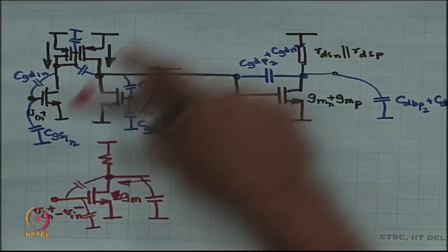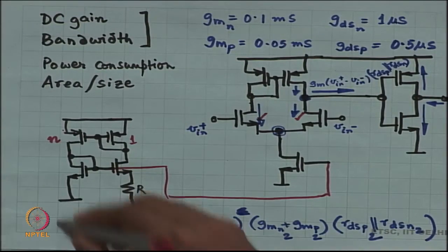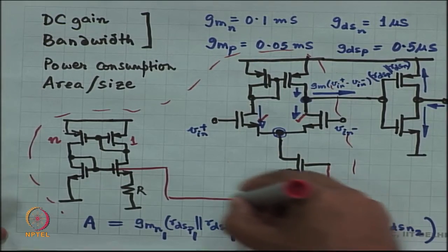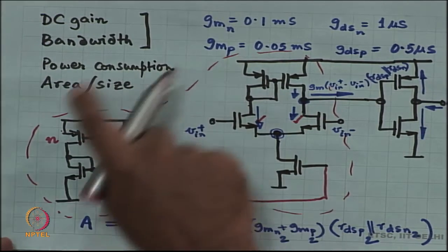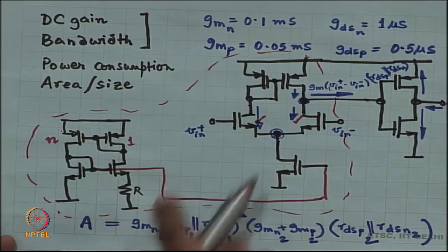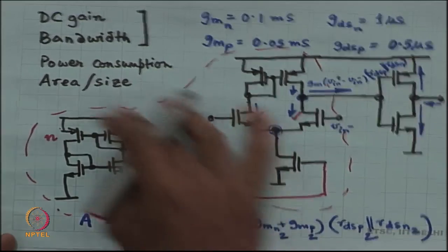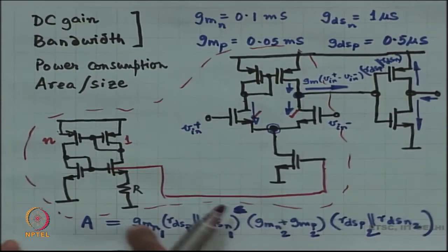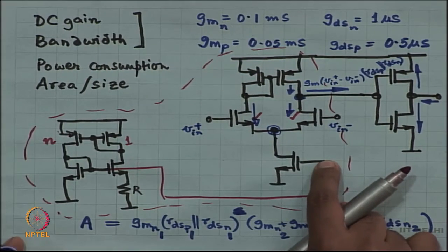So, you are going to model this entire network. By the way, all of this is nothing at DC, at small signal increment. In the small signal incremental picture, this is a ground, because this does not change with signal. None of the currents and voltages here change with signal. So, therefore, this voltage is fixed with signal, which means that this is ground in the small signal.